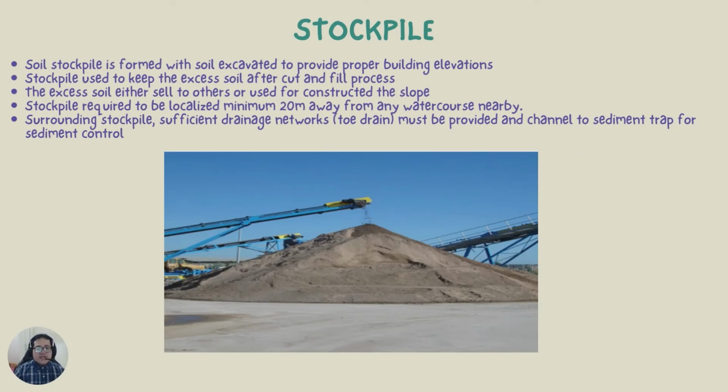So the last BMP is the stockpile. Soil stockpile is formed with soil excavated to provide proper building elevation. Stockpile is used to keep the excess soil after the cut and fill process. The excess soil is either sold to others or used for constructing the slope.